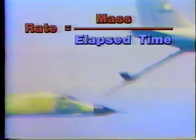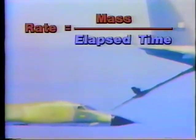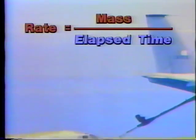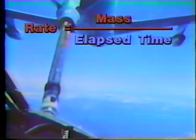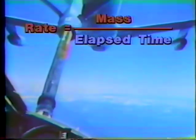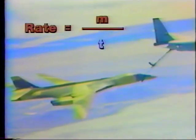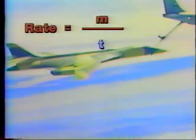The second way to measure how much in a fluid system is to measure the mass of a fluid that moves over a period of time. A pilot is not as concerned about the number of gallons of fuel he takes on as he is with the weight of the fuel, because that affects the performance of the aircraft. So in this case, the fuel flow rate is measured in pounds per hour, or kilograms per minute.